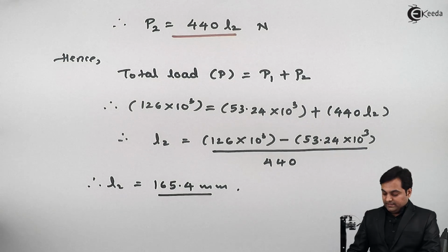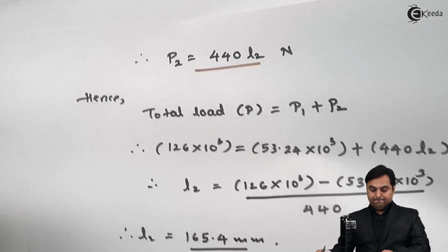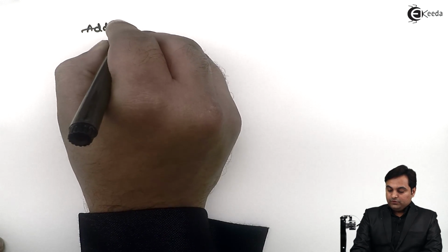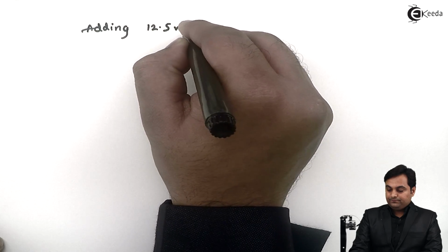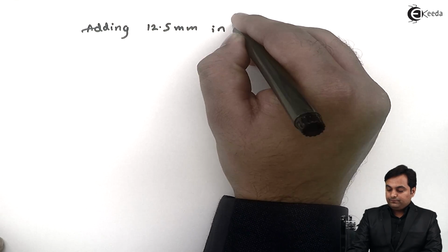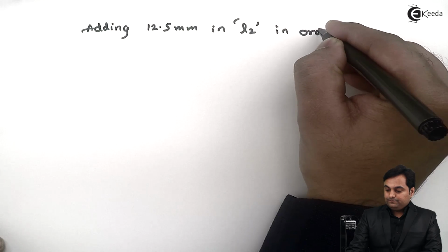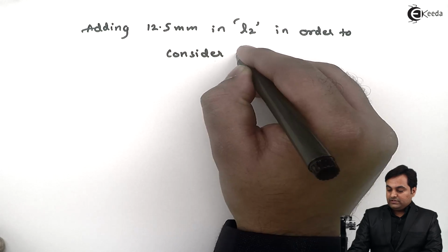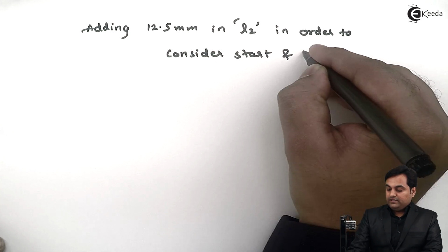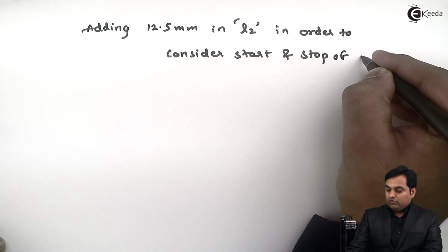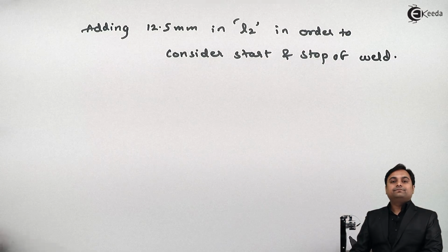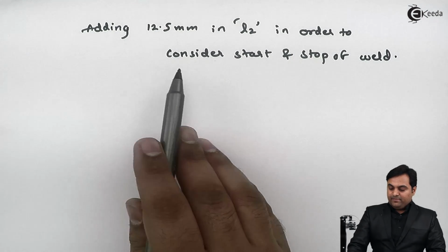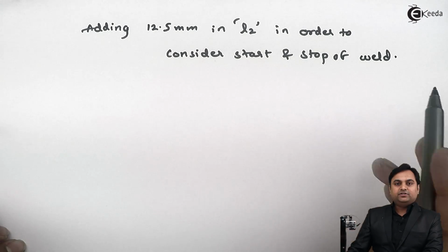After getting L2, I am adding 12.5 mm to L2 in order to consider start and stop of weld.